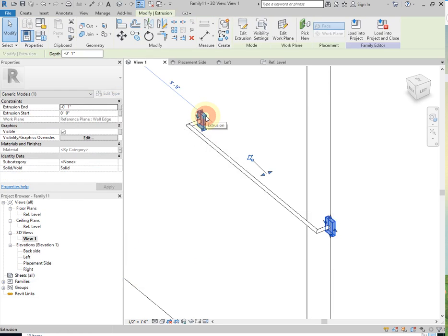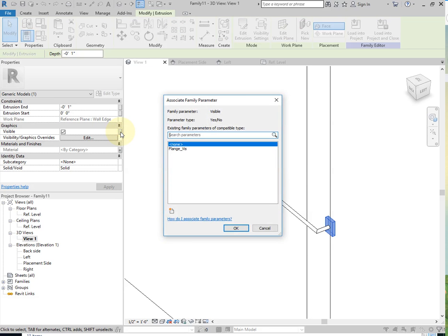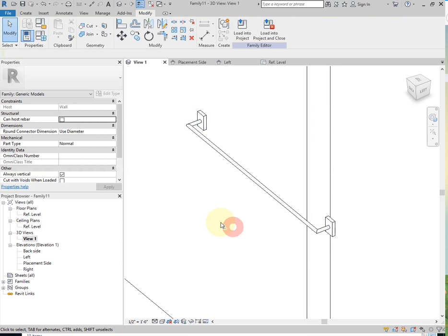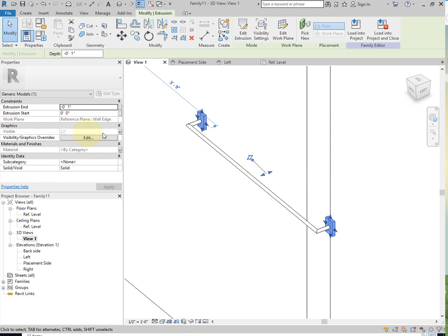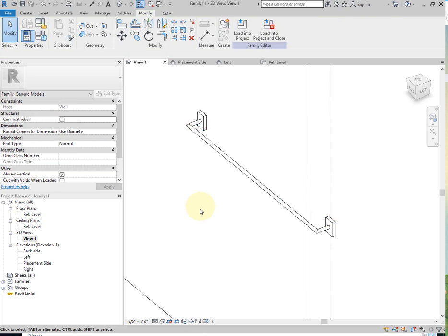Click on the flanges. There's a visibility in the checkbox. Click on the little box at the end, like I did for materials. Assign flange visibility to it, and uncheck it. So look at it. Visibility is checked. We can preview visibility in this without inserting it into a project. The very bottom is a preview visibility on-off function.